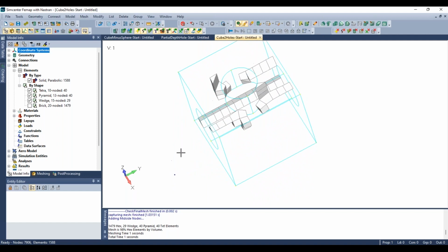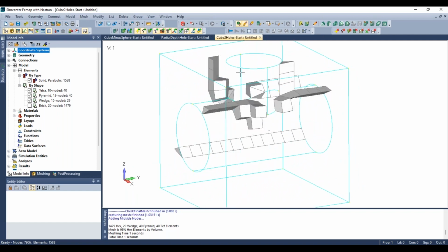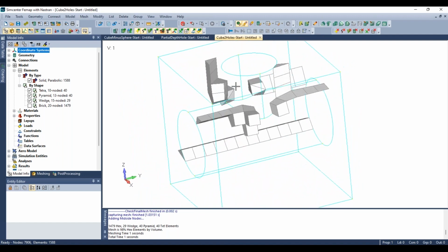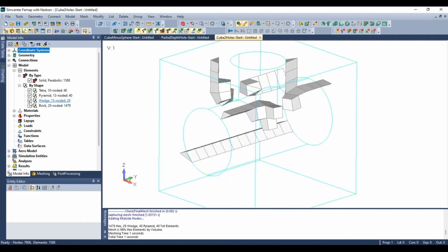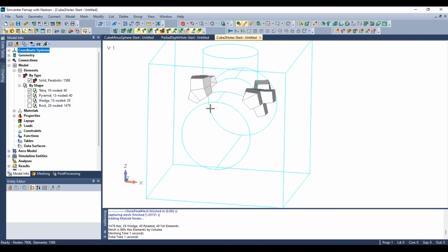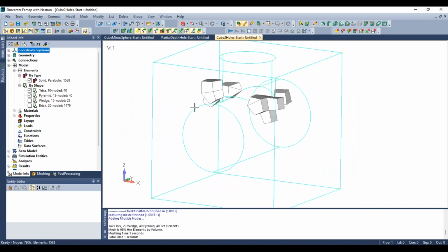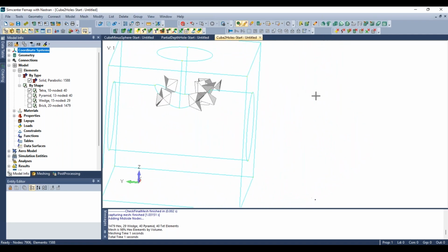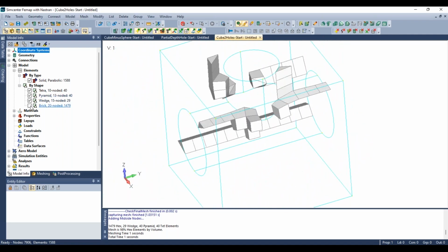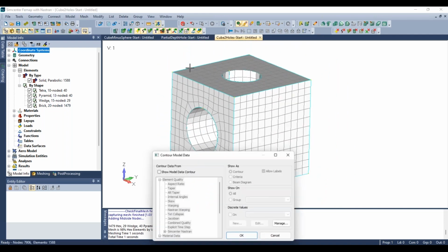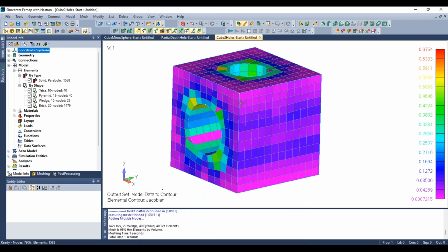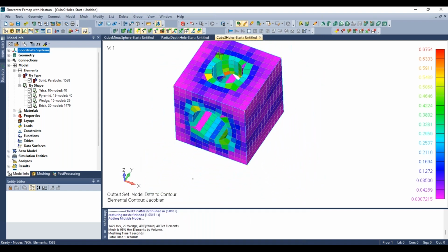I guess maybe if our high stress areas were around the openings, which is likely, because that's a likely stress concentration, this might be a concern. But it's definitely dominantly meshed with bricks. There you can see our transition pyramid and tetrahedral elements. And then when we hide the pyramids, those are just the tets there. So everything with a grain of salt. Sometimes this tool works very nicely. Sometimes it doesn't, but it's all about investigating the resulting mesh that you get.